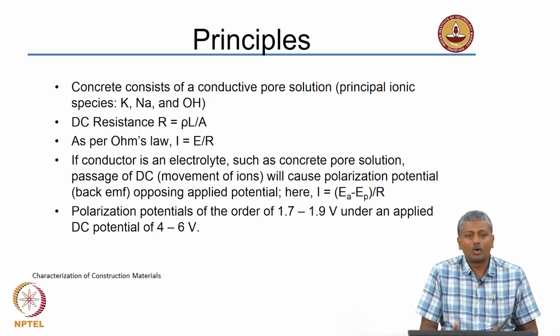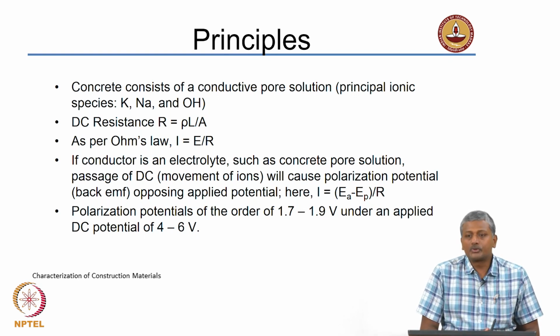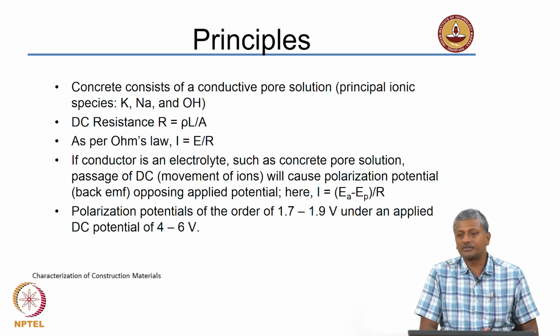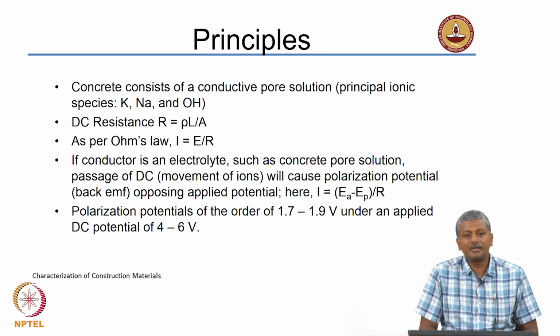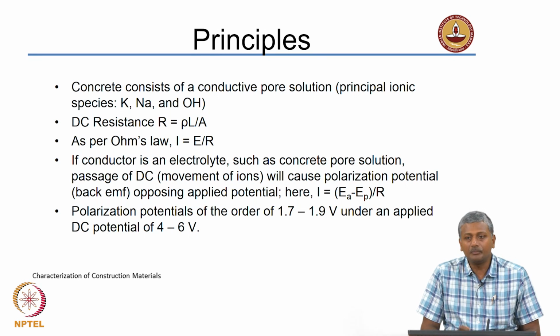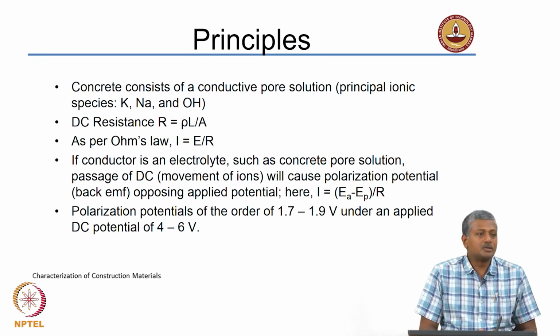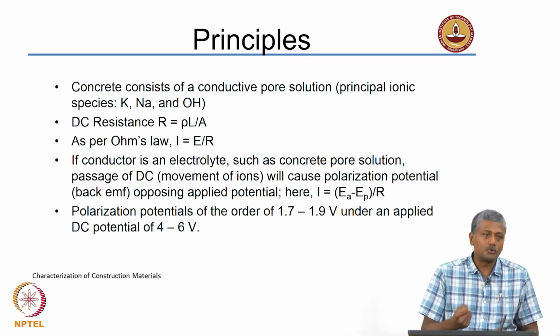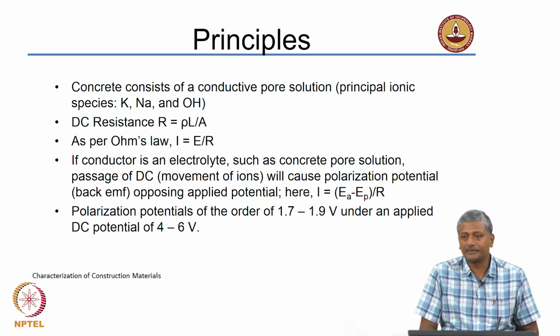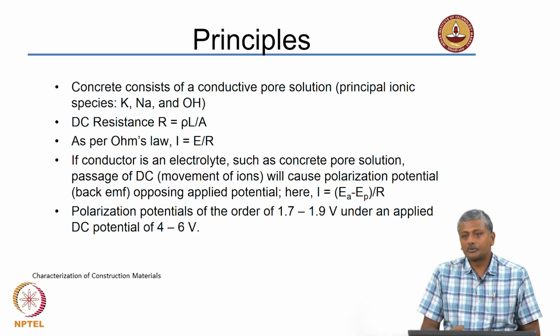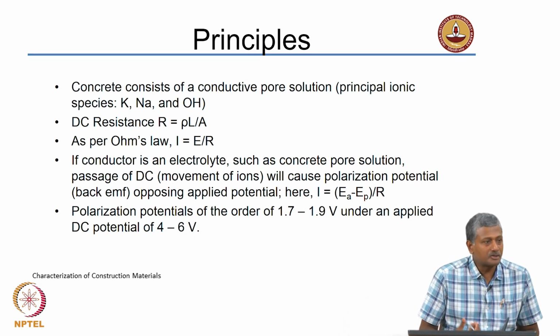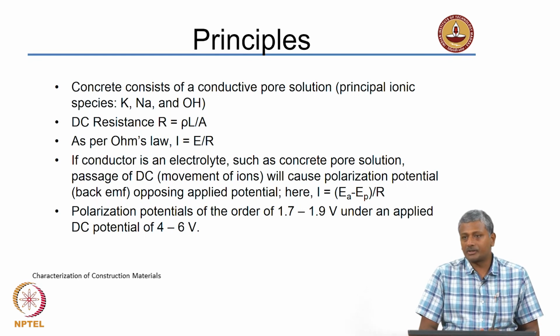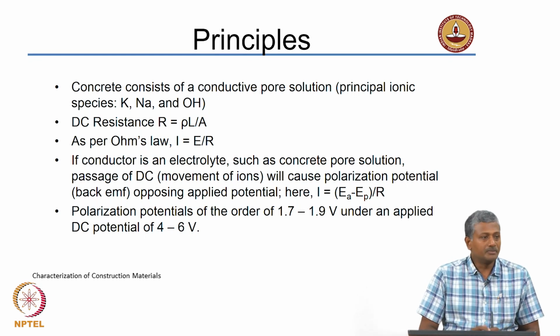But it is not just plain water that is filling the pores, it is a pore solution that is caused because of the dissolution of certain species from the cement, and primarily these are alkaline species like sodium and potassium, and to create a balance in the pore solution you always have hydroxyl ions also in the pore solution. So, if you take a mature concrete and you were able to squeeze out the pore solution in the methodology that we discussed earlier, the only ionic species that you will find in any appreciable concentration would be sodium, potassium and hydroxyl.